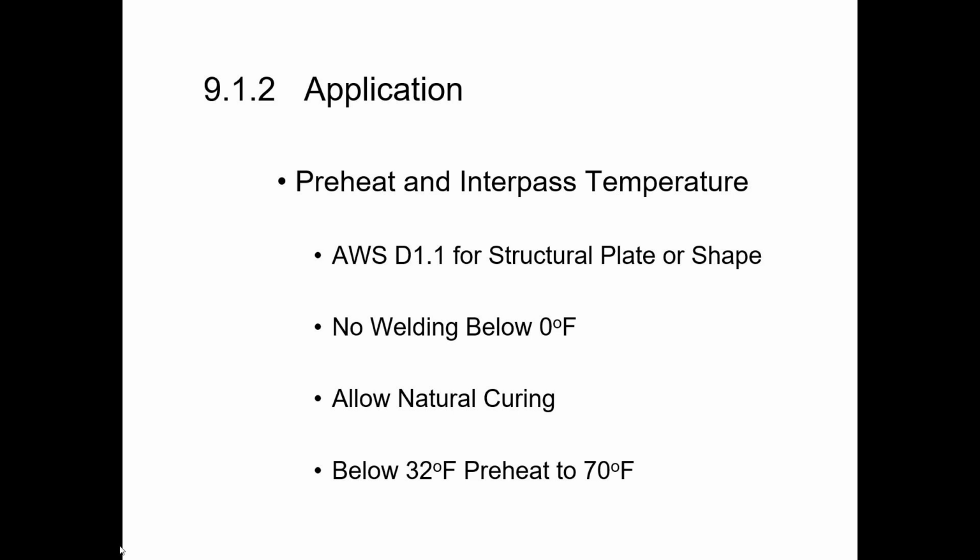After welding is completed, the bars need to be allowed to cool naturally to the ambient temperature. Any kind of accelerated cooling is prohibited. Again, we're trying to ensure that we've got these long, slow ramp up of temperature and cool down periods so that we don't embrittle the material, the steel. And I already mentioned number 4, where it is impractical to obtain chemical analysis, the carbon equivalent shall be assumed to be above 0.75. And that's just saying if you don't know what the CE is, you have to assume worst case and preheat to 500 degrees.